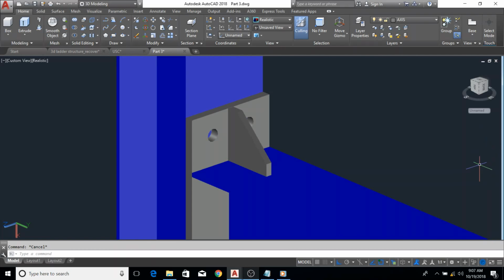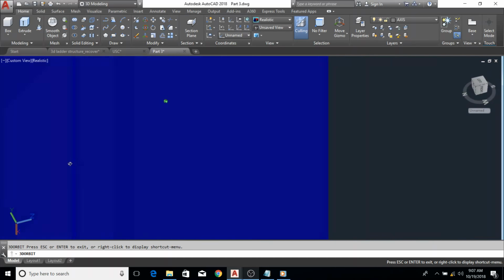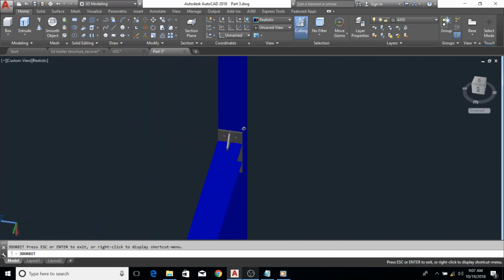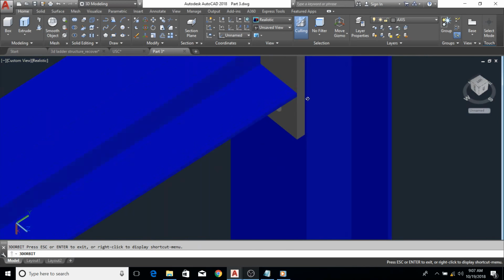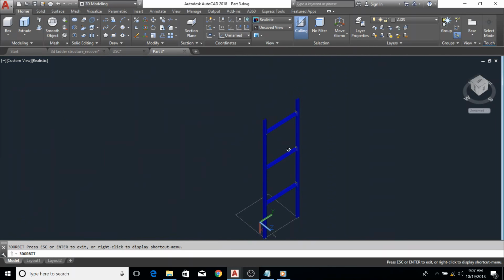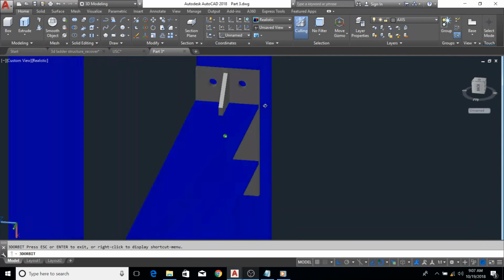And sometimes this thing that I'm using here, I don't know if you did notice that there is a palette here where I used to select the orbit command, but sometimes it does disappear and come back. Don't really get mad over that. What I normally do is I will just press ORB. It's simple as that. Then the ball comes, the orbit command will be activated. That is why it's very important to master the shortcuts, so that in case of any eventuality, you can easily be navigating your way whilst you'll be repairing the icons that you needed.